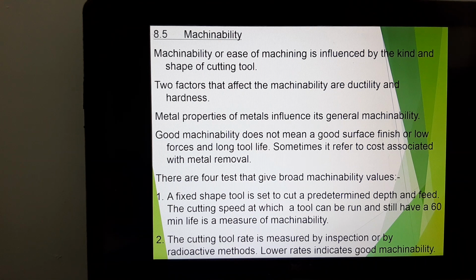Please remember that in exams, the moment I give you 2 marks for a structured question, I may just give you a case scenario in an industry. A product has been machined, the tool broke during the machining process, the surface was rough, the cost involved overall was high, and the power consumption was high. I would not consider it a good machinability, and I expect you to explain to me in terms of these 4 factors. So I would expect an answer as such.